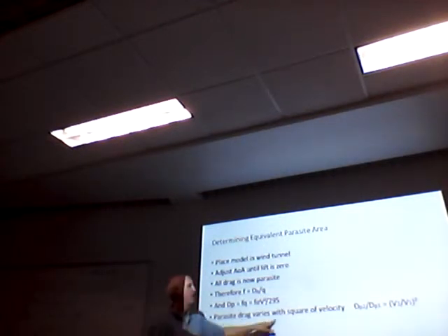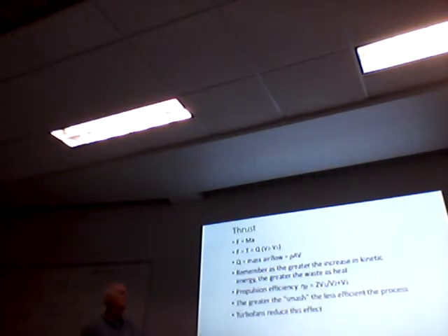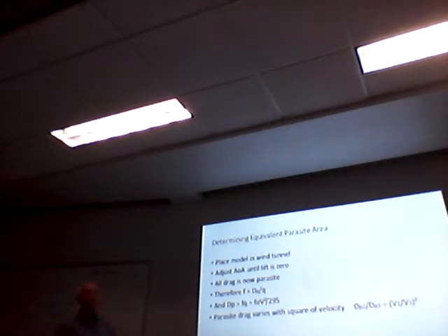Parasite drag varies with the square of velocity. That's important. Not the formula, but just that fact. Okay? Just that fact. Parasite drag varies with the square of velocity.